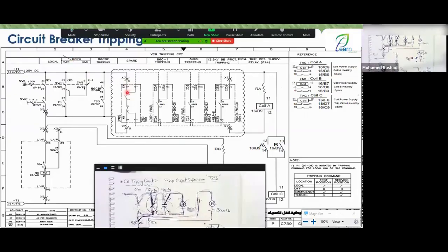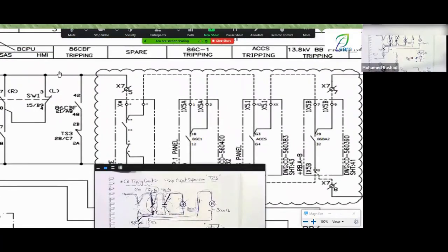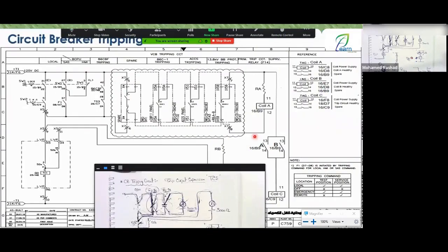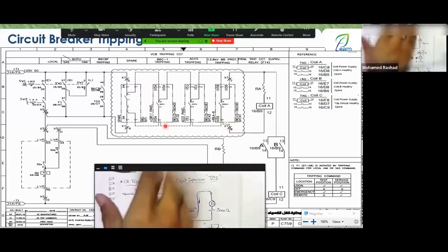You'll see it in the protection circuits. Here it goes to the protection on a terminal block, enters the contact head, then exits to another terminal block, and so on for the next protection, and so on for the next protection. All right, boss, until it went to a resistor, or here along with a coil and return. Of course, this connection is wrong. It should go to the contact head and return.